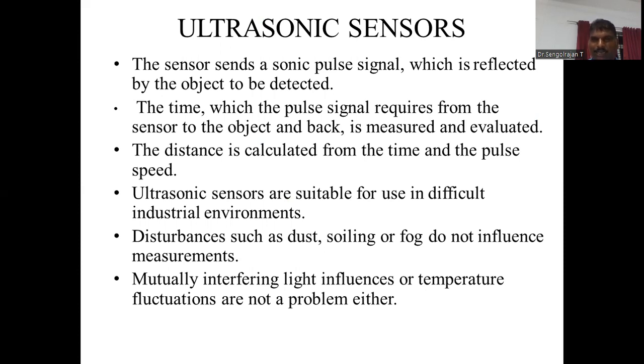That is, an ultrasonic sensor sends a sonic pulse signal which is reflected by the object to be detected. The time that is required by the pulse signal from the sensor to the object and back is measured and evaluated. The distance is calculated from the time and the pulse speed.